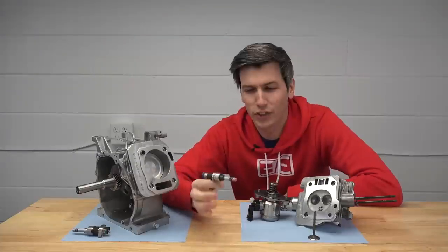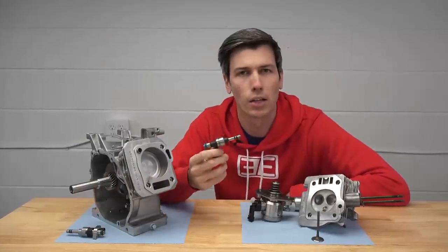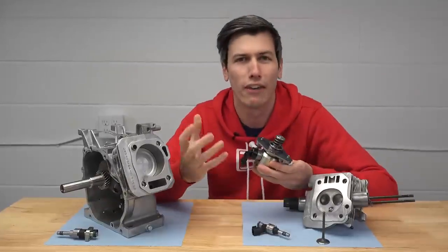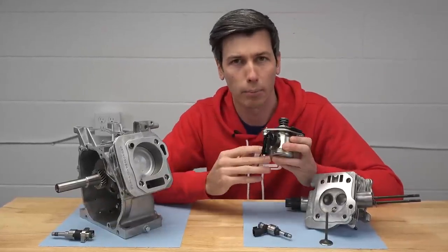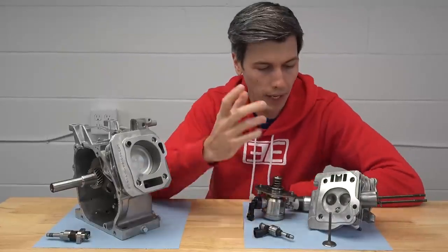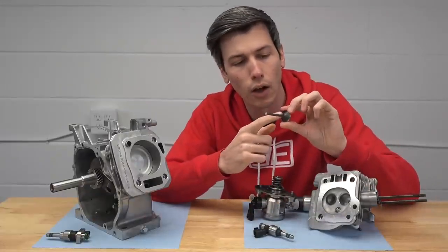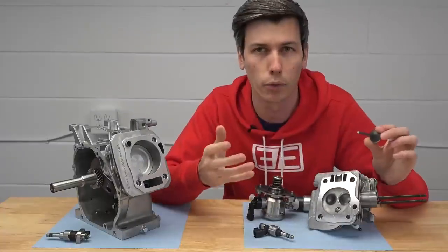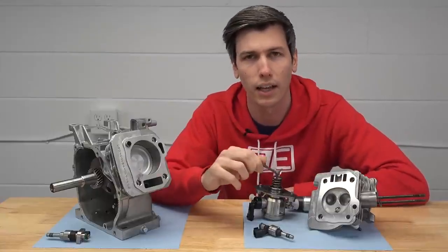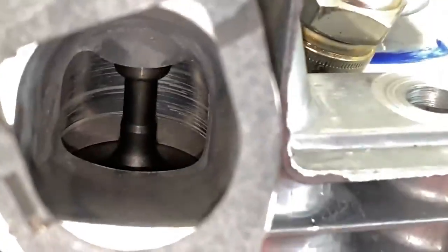But direct injection is certainly not without its flaws. Because the components involved are seeing much higher pressures, a lot of them are going to be significantly more expensive. Also, because you're using higher pressures, you're going to have higher parasitic losses. You have to drive this high pressure fuel pump in order to make those really high pressures to inject the fuel into the cylinders. And of course, now that you don't have port injected fuel, you're not actually spraying any fuel onto these intake valves. So great, your air-fuel ratios are more precise. However, you don't have that cleaning power of the fuel to clean off these intake valves. Over time, depending on the design, that could mean having a buildup of carbon deposits within the intake.